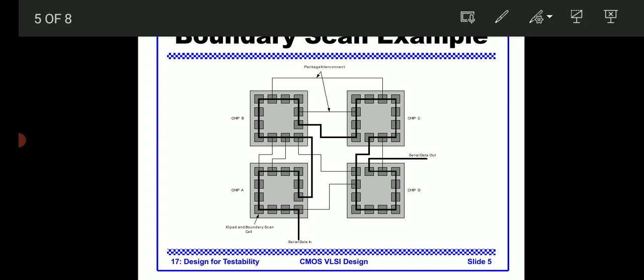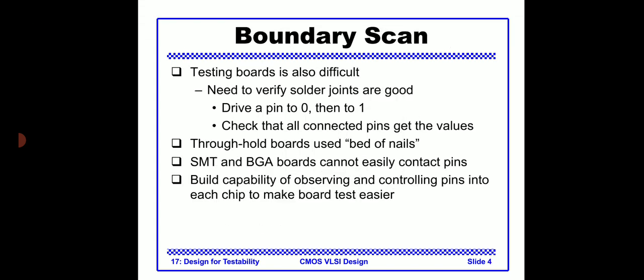In normal operation the circuit under test receives its inputs from the other modules and performs the function for which it is designed. During the testing mode, the test pattern generator applies a sequence of test patterns, and the test responses are evaluated by the output response comparator. In the most common type of BIST, the test responses are converted by the output response compactor into signatures, which are compared with the golden signature stored on the chip, and the error signal indicates whether the chip is good or not.